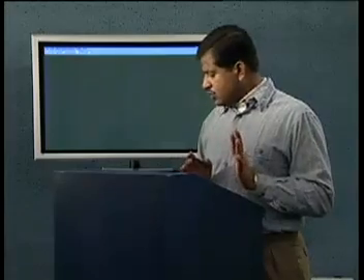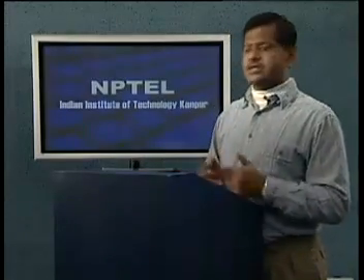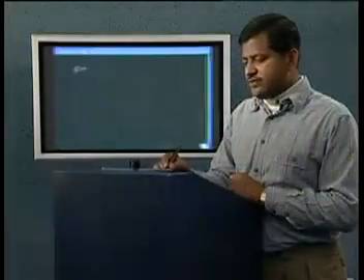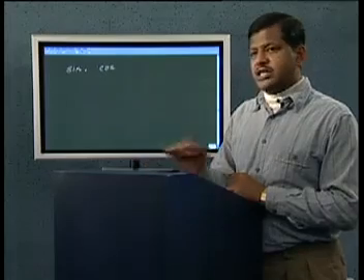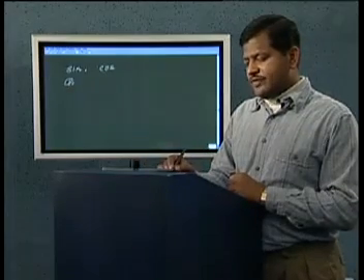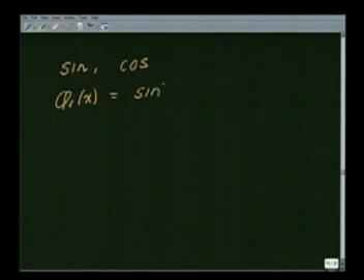So this is how you would construct the Rayleigh-Ritz solution for a variety of problems with different boundary conditions, different load vectors, different material coefficients using a polynomial approximation. Now nobody tells us that we should use a polynomial approximation. We can also use sine and cosine functions. For example, we could have chosen phi i of x equal to sine n pi x by L.